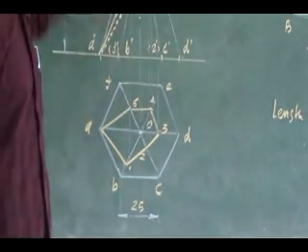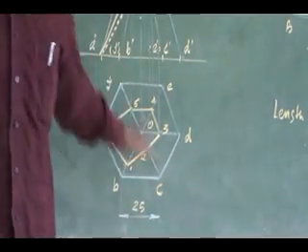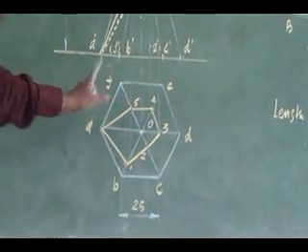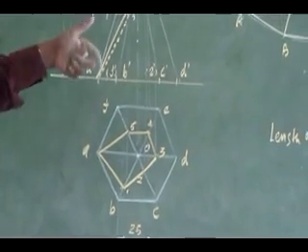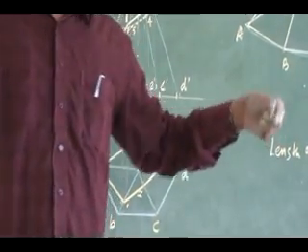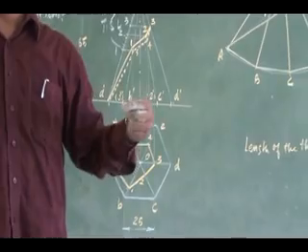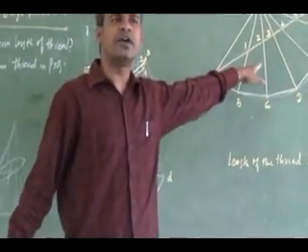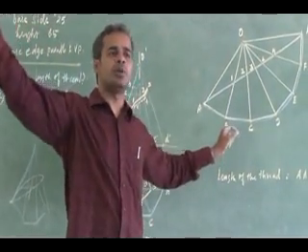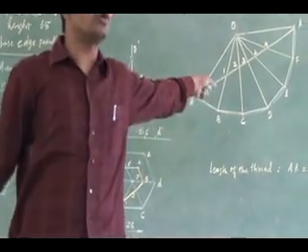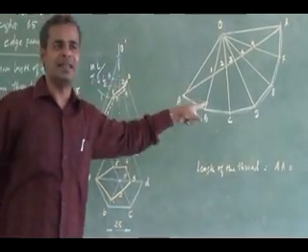The shortest route in the top view, right? Is it clear? Do you have any clarification? This is an important problem. Okay. Shortest length required. In a pyramid, if you want to find it out, you have to go for the development, you have to connect the point to point with a straight line. That will give me the shortest length of the thread.